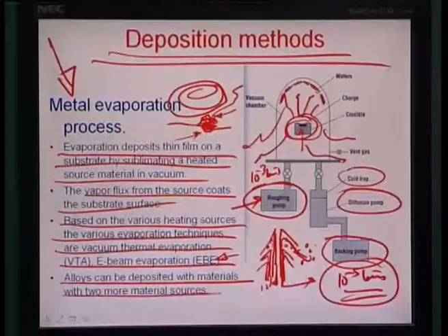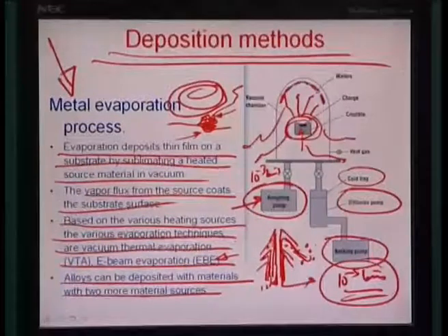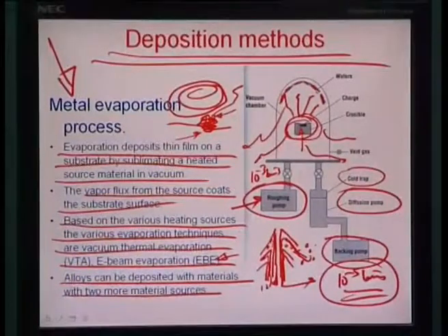And then there can be other techniques or other means of heating for depositing the vapor of the metal on the top of a silicon substrate. You can also deposit alloys using this by using 2 or more materials conveniently in a certain ratio. In this case it may be a wire made up of alloy, or maybe just by percentage weight you could do the 2 metals as globules and put it inside the crucible and then evaporate them together.